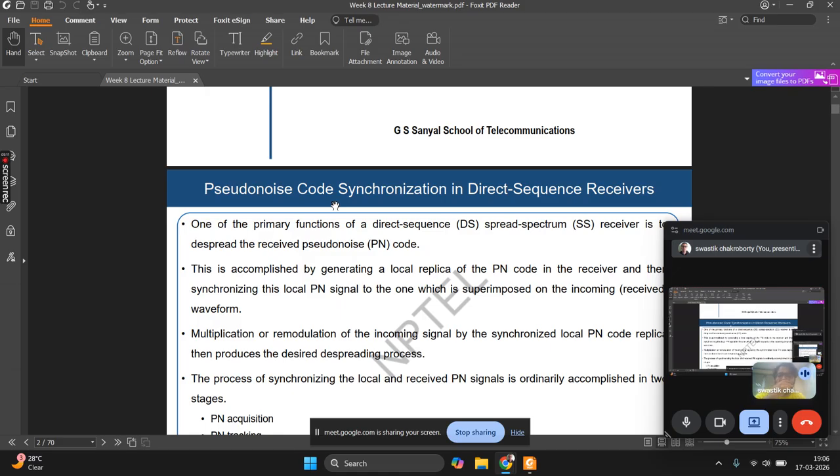So the first thing that we have to note is in DSSS, all the codes generated at the transmitter and the receiver, the PN sequence codes, should exactly match. If there is even the slightest mismatch of codes, even one bit synchronization error will cascade into a proper error.